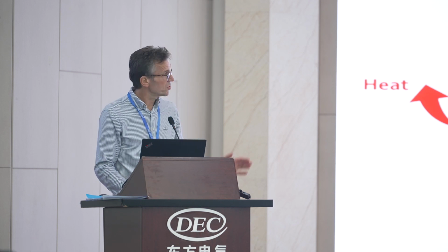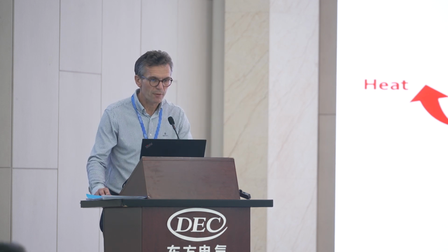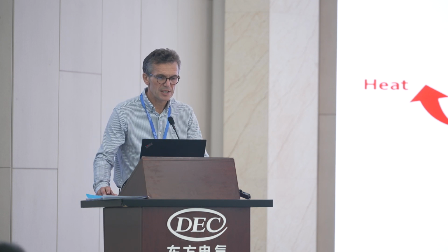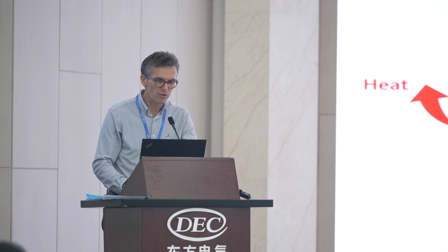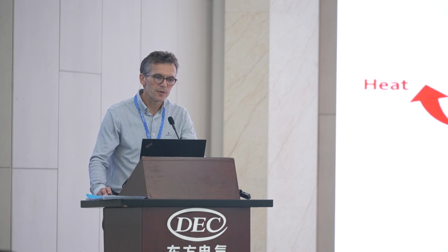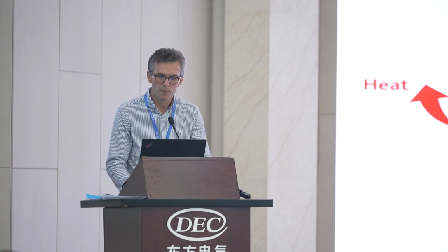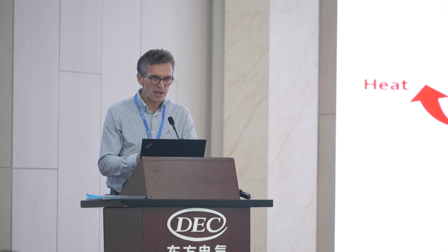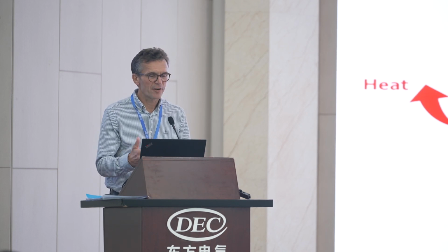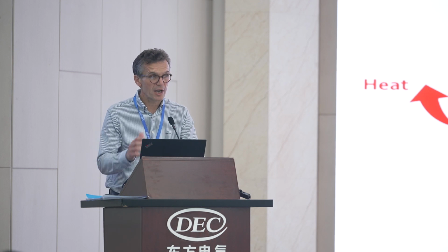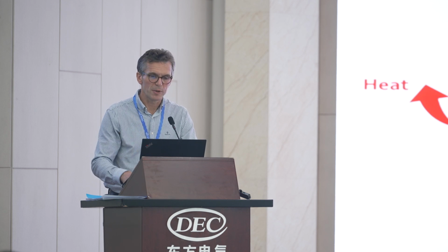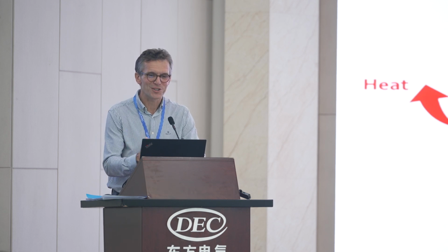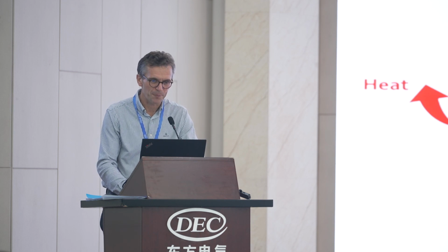It takes up the oxygen in the air reactor, as you have heard already. This is a very rapid oxidation at high temperature, about 1000 degrees in the reactor. And this oxygen is brought to the fuel reactor where it is used to combust the fuel. The oxygen carriers also transfer heat to the fuel reactor, because the fuel reactor is not so exothermic, so it will need some heat from outside to sustain the combustion process.